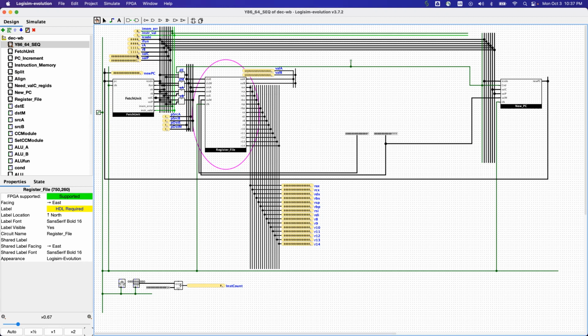For running this simulation, I just connected val E and val M with a constant value, F and F. Also, the condition code for the control module destination E, and the condition code to the PC update, I set to just zero value, since we don't have an execution unit, so we cannot execute jump or conditional instructions with condition code correctly.